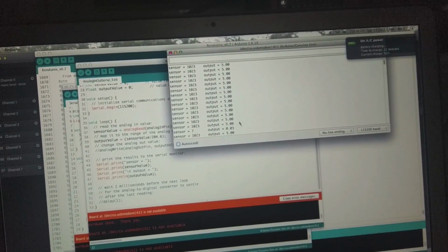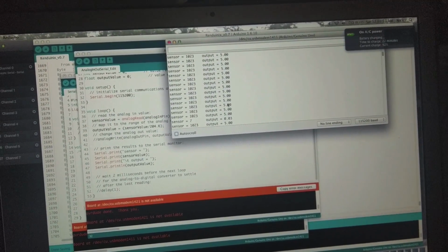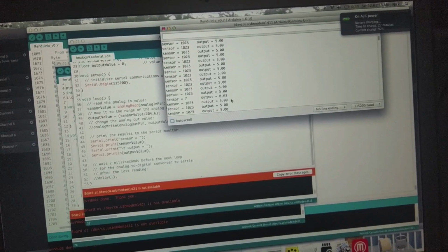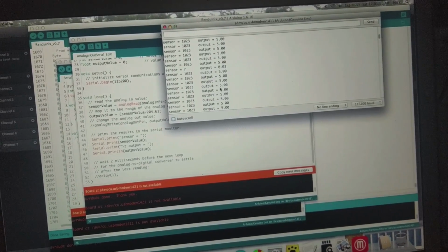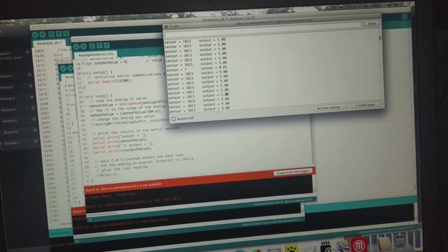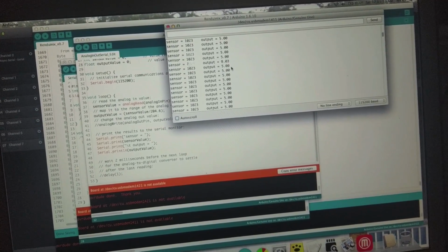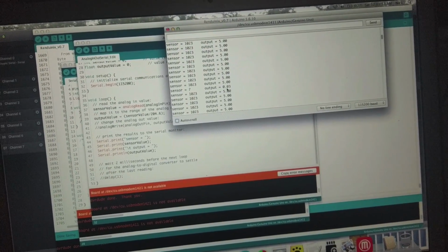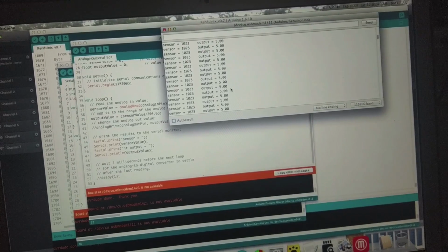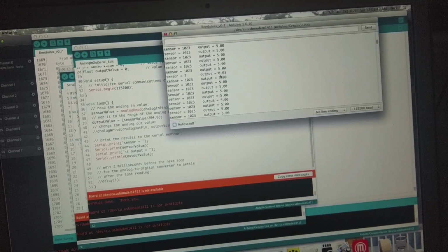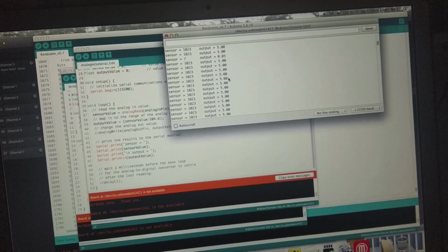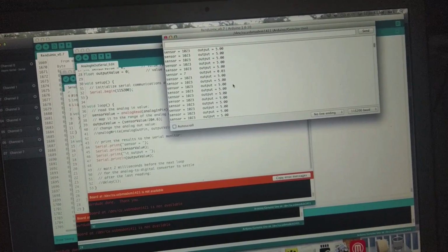So I decided to check the ECU side just to see what that was doing, because I know that this one works. And on this one, it looks like you get a perfect 5 volts, so it's being pulled up properly. And when it goes low, it goes down all the way to 0.03. And you see that a couple times. So that's a very defined high and low. That's almost perfect. So that's interesting.